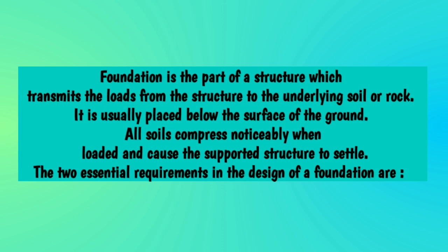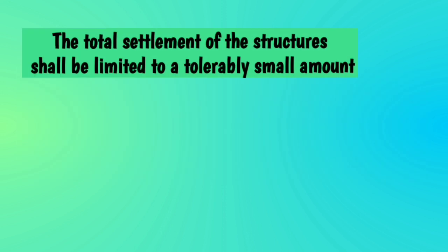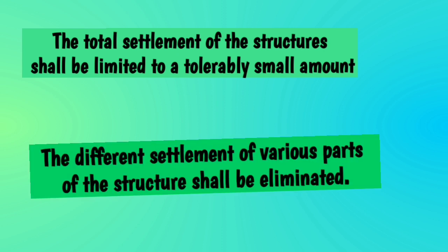Foundation is the part of structure which transmits the loads from the structure to the underlying soil or rock. It is usually placed below the surface of the ground. All soils compress noticeably when loaded and cause the supported structure to settle. The two essential requirements in the design of foundations are: first, the total settlement of the structures shall be limited to a tolerably small amount, and number two, the differential settlement of various parts of the structure shall be eliminated.